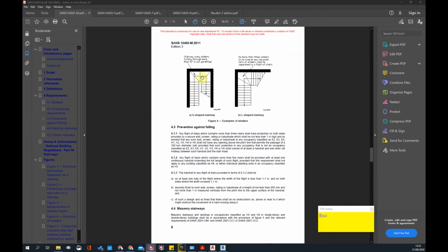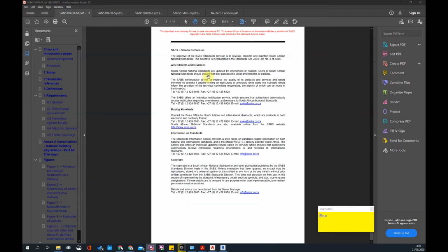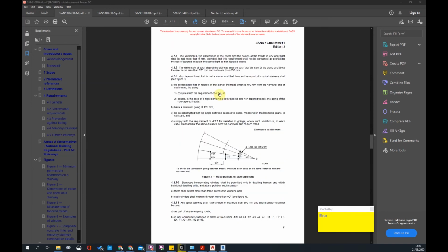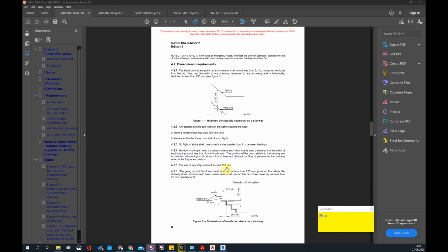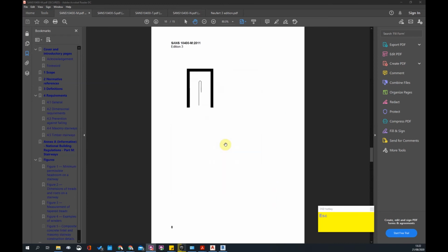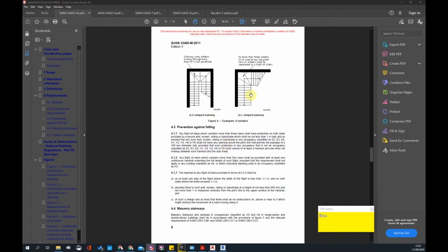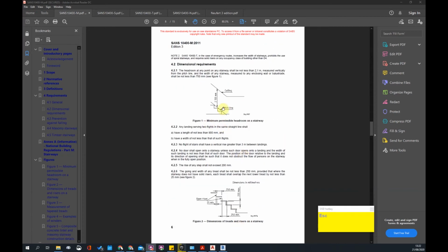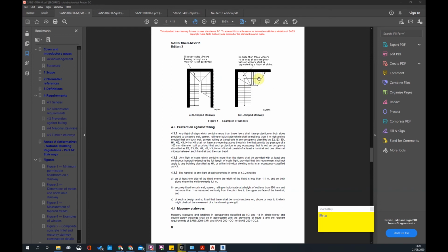In South Africa, generally we don't have those weird shapes. They're trying to force you to have these type of steps. Okay, and you can draw those in. You can literally use that draw tool to kind of establish those type of steps. In Europe, generally they will use those other type of steps where I showed the angle changes slowly. But generally in South Africa, it's very hard to cast a step like that out of concrete. It's very hard. So generally you could have this approach going on. That's fine. You can do that kind of landing. But then you'll have to draw the step in.